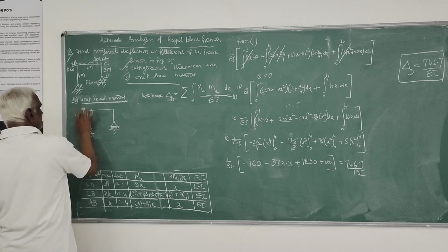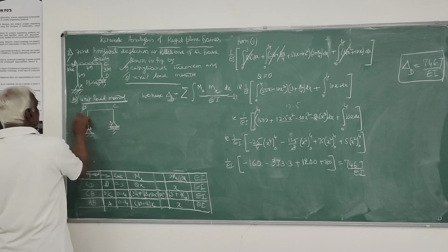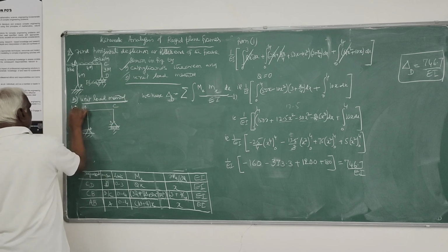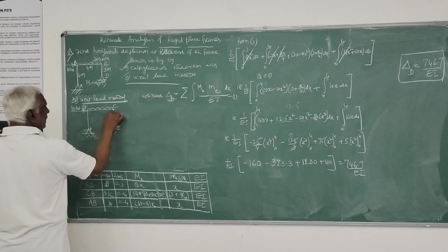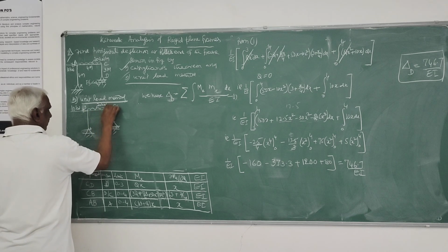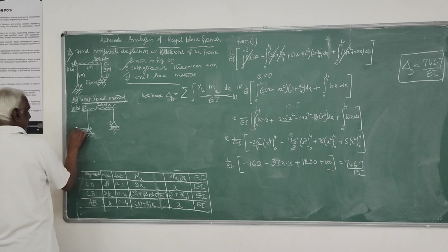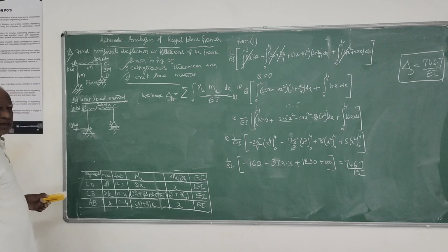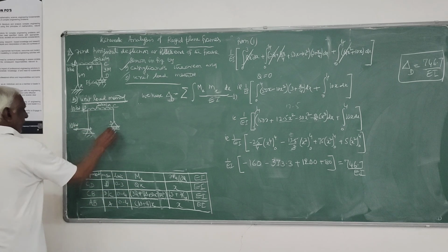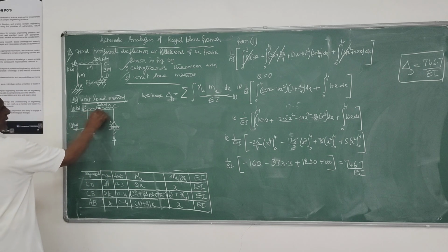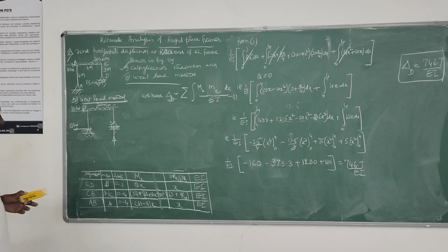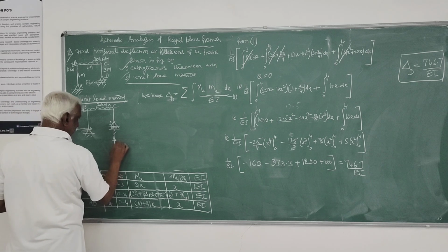This is the frame. So A, B, C, D. This is that 10 kilonewton you are getting, and this is 20 kilonewton per meter. So here you will get reactions 10 kilonewtons. Earlier you had 10 plus Q because I applied Q also directly. Here I will take it separately that unit load. And here the reaction, so it is 10 into 4 plus 20 into 4 into 2. That is 160 plus 40, 200 divided by 4, 50.